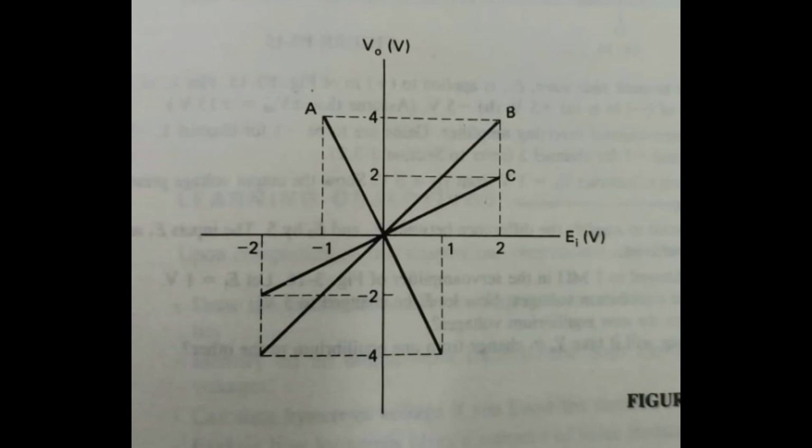And for a non-inverting amplifier, the formula is Vin into 1 plus R2 by R1. See, our resistors always come in some standard values. Now, if I give you the transfer characteristics, from the transfer characteristics also you can calculate the gain. How, I will tell you.